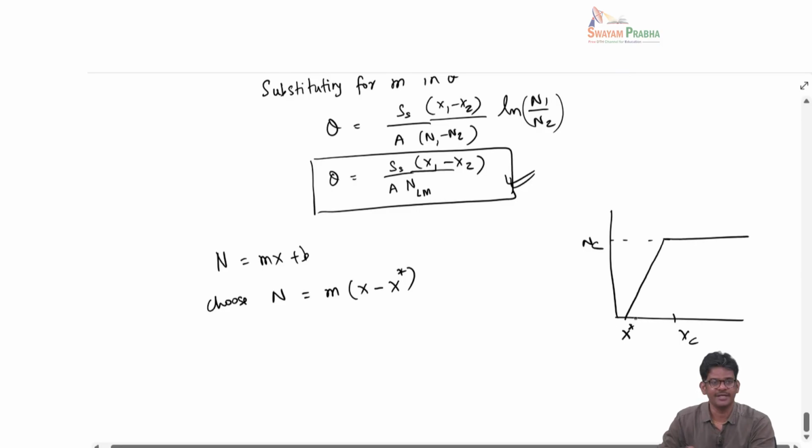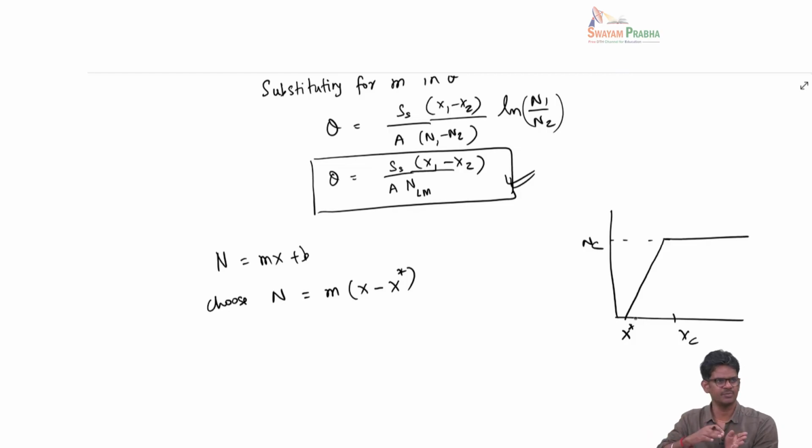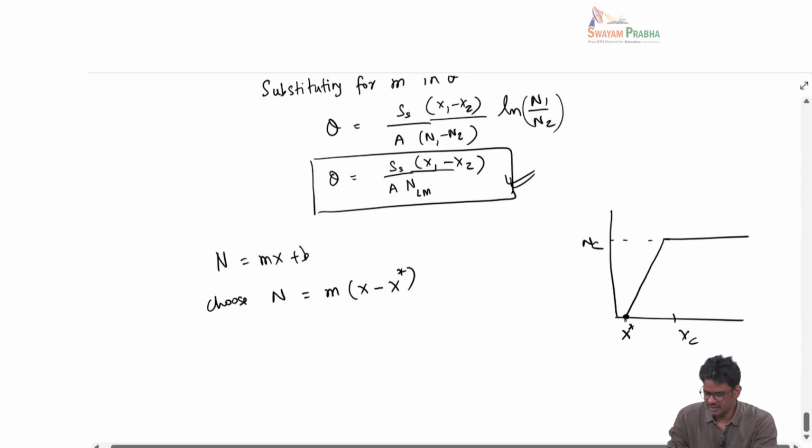That means I am thinking about the falling rate as one single phase. I am not distinguishing between surface drying and internal moisture drying. The entire falling rate can be assumed to be a straight line. So this drying curve is constant and then falls linearly up to the equilibrium moisture content X star.